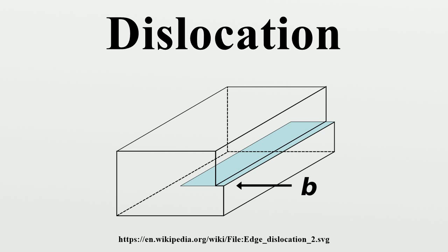Observation of dislocations. When a dislocation line intersects the surface of the metallic material, the associated strain field locally increases the relative susceptibility of the material to acidic etching, and an etch pit of regular geometrical format results. If the material is strained and repeatedly re-etched, a series of etch pits can be produced which effectively trace the movement of the dislocation in question.